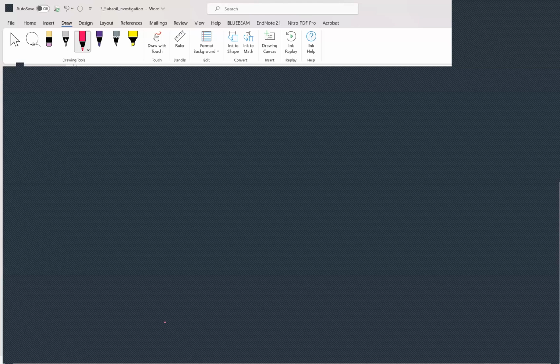So you can look at the nature of the soil in this area. For example, we have a river here, some soil type here, and some heights here. So this aerial photo can be considered one of the sources to use in the desk study process.